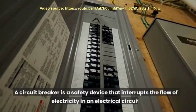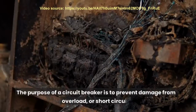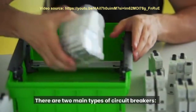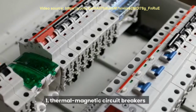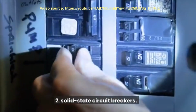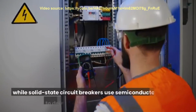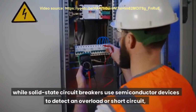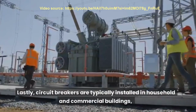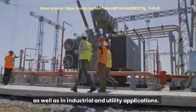A circuit breaker is a safety device that interrupts the flow of electricity in an electrical circuit. The purpose of a circuit breaker is to prevent damage from overload or short circuit. There are two main types of circuit breakers: 1. Thermal magnetic circuit breakers. 2. Solid-state circuit breakers. Thermal magnetic circuit breakers use a combination of heat and magnetic force to trip the breaker, while solid-state circuit breakers use semiconductor devices to detect an overload or short circuit, and then interrupt the flow of electricity. Lastly, circuit breakers are typically installed in household and commercial buildings, as well as in industrial and utility applications.